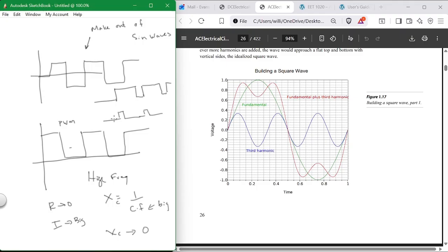Another place they are interested in those high frequency signals is motors in general in factories. So they put an accelerometer on the motor. What's an accelerometer? It reads acceleration and gives you a little voltage out for acceleration. So as it jiggles, as it vibrates, it gives you a voltage. If something is jiggling, the high frequency movement, the high frequency vibrations will show up, and they will discover which of those high frequency gyrations cause bearings to go bad. So you can predict when a bearing goes bad in a motor.